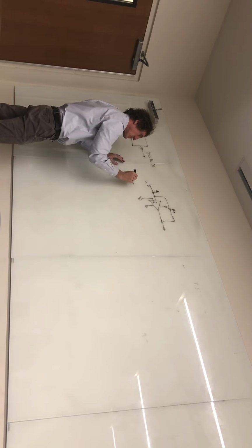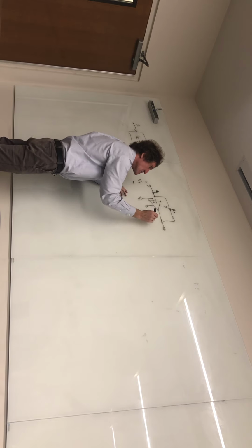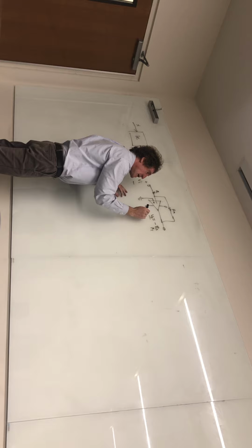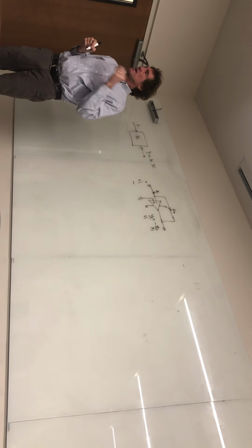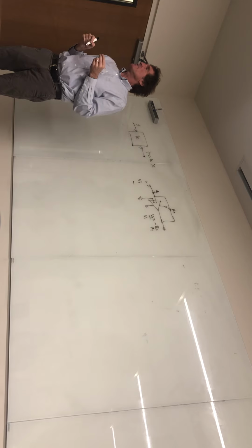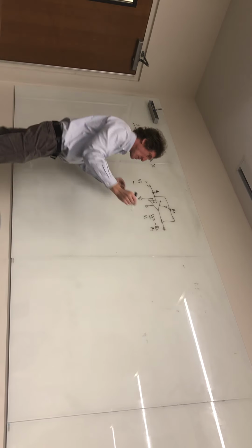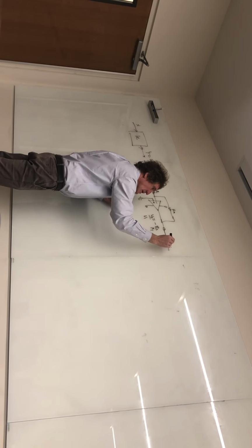Now this is going to be the input voltage. At this point, V out here is equal to minus R2 over R1, and I'll call it V out over V in. That's the transfer function. Do y'all agree with that? Mm-hmm. It's minus R2 over R1. We can prove that. We don't need to. We've seen it too often. Now, I'm going to put next the follower. This is going to have just R1 here.